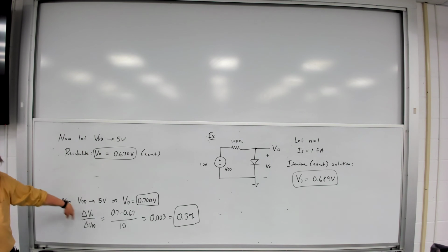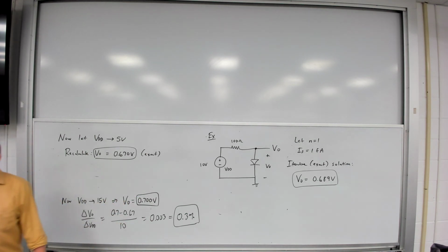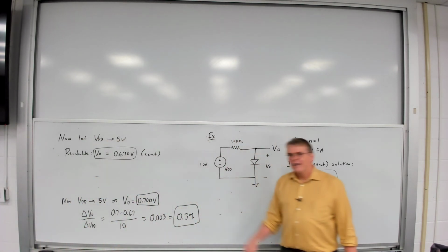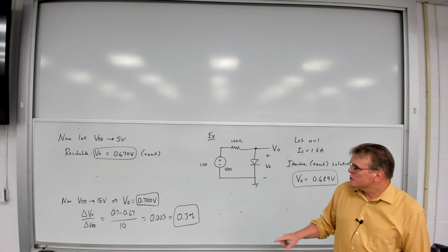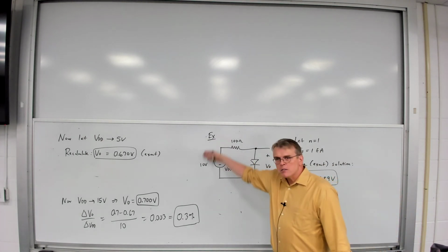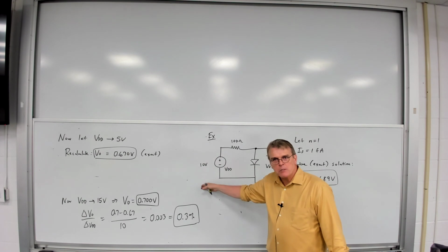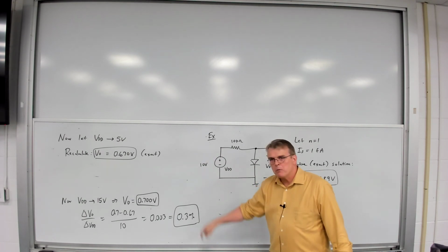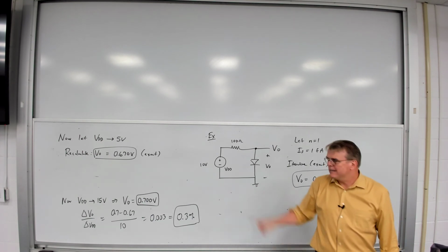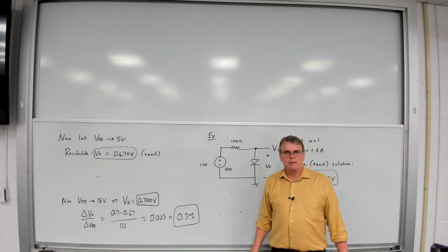It changes very little, and over that very broad range, I get only a 0.3% change. Well, this is good. What we have here is a circuit where I have an enormous change, plus or minus 5 volts, plus or minus 50% value shift, and yet the output only changes by 0.3%. That's a very desirable result if you need to have a stable output voltage.